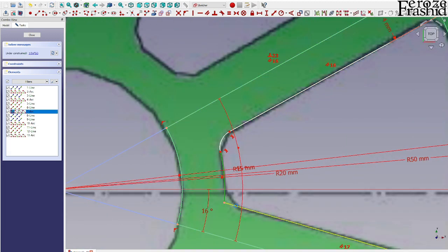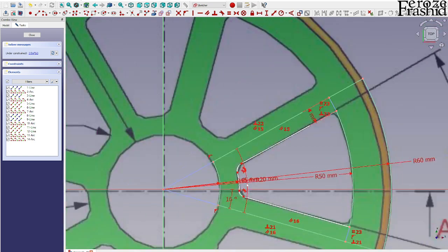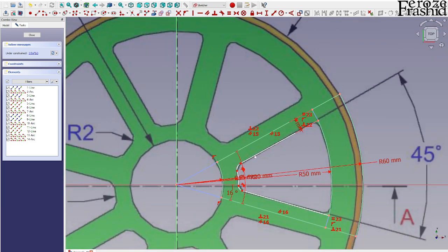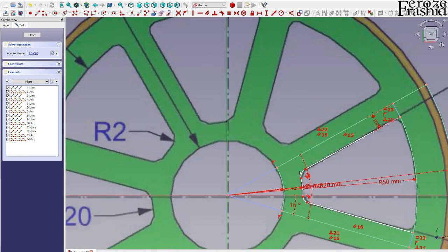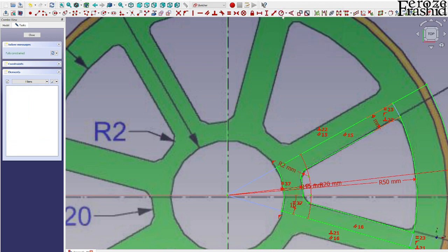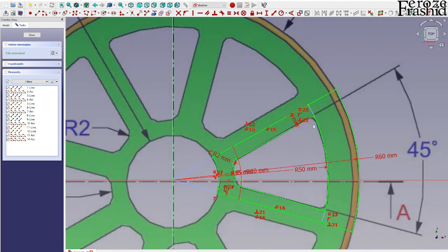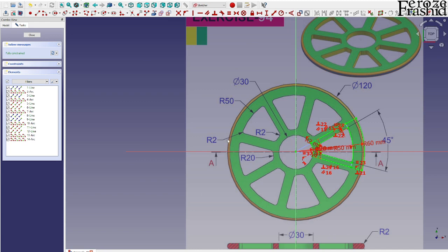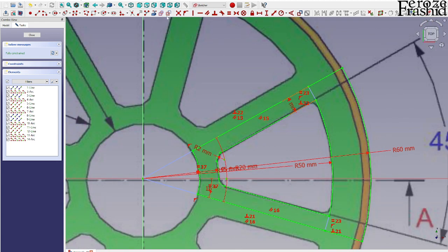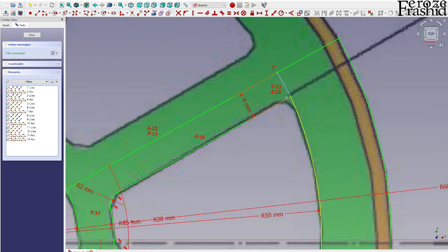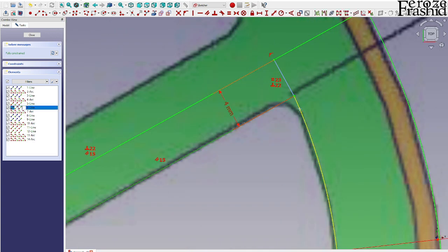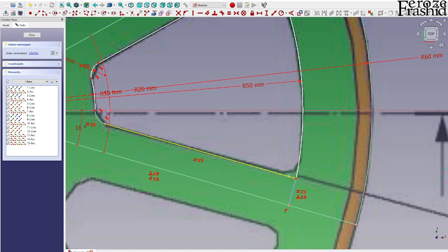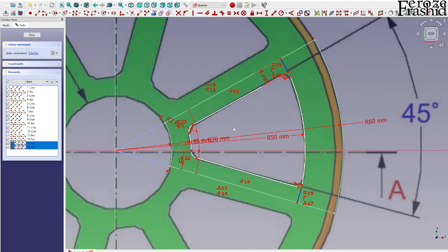Right, so now we have this corner which is 2mm radius, so these two will be radius 2mm, and we can do the same thing on here. Let's see, it's the same 2mm radius as well. So we are taking constraint preserving sketch fillet and doing this sketch filleting, and let's make these two equal to this one.